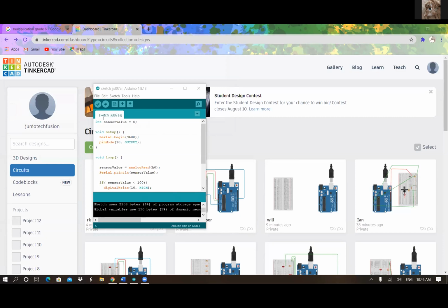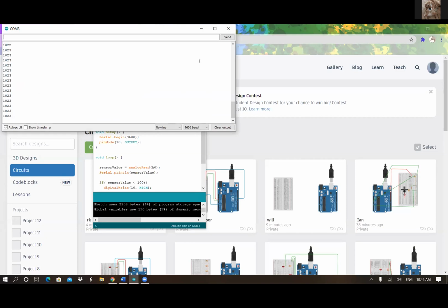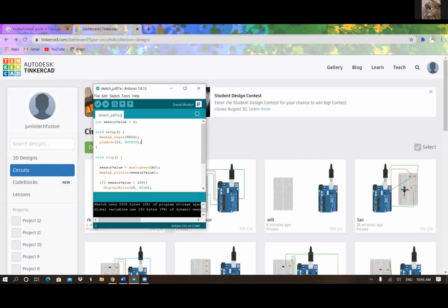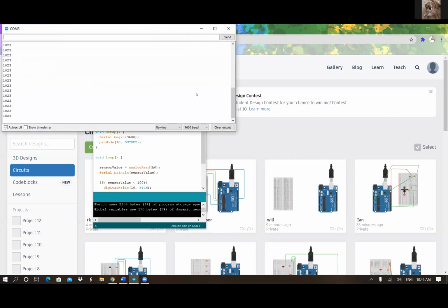Okay, Kranti, can you click on tools and show us which port you're using? Oh, okay, so you have the numbers. Okay. It's at maximum, whatever she's reading. So what happens when you cover the sensor? I think it's a schematic problem there. I think she's just short circuiting the. We need to trace your wiring to make sure.